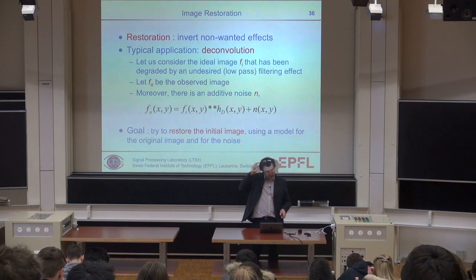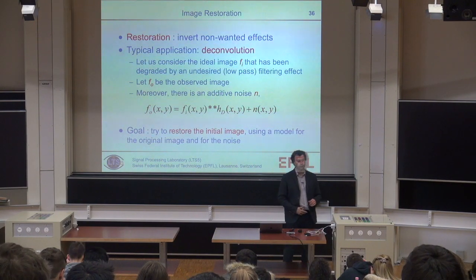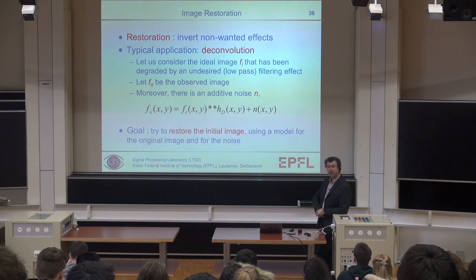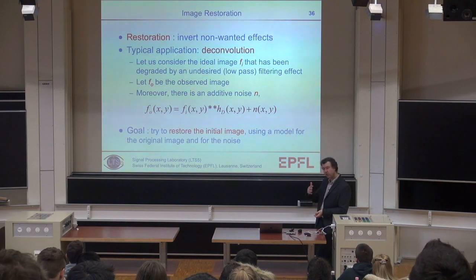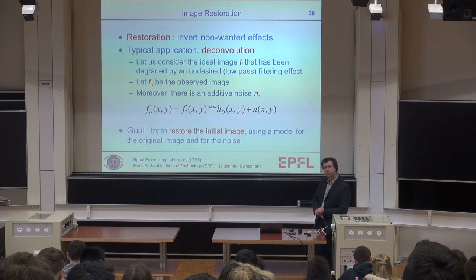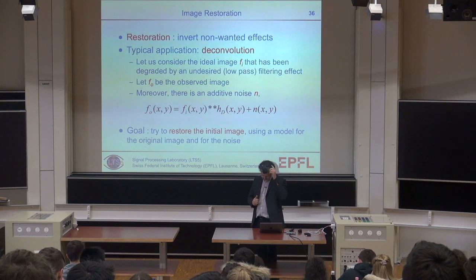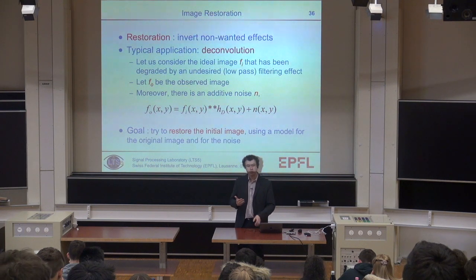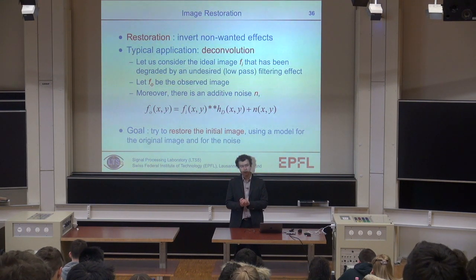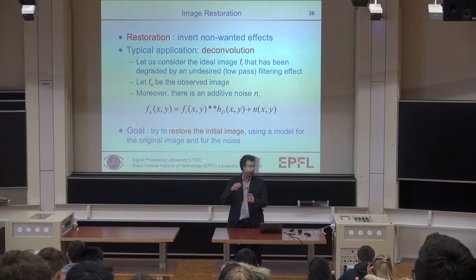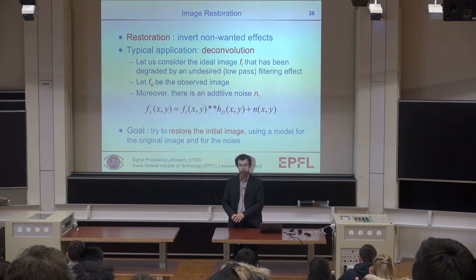But obviously, you want to deal with the fact that you have noise. And now I want to come with you and finish this course with this very interesting domain of image restoration in a more systematic way. Let's try to have an intuition. Let's try to think of what I just said. When do you want to do a high-pass filter? When you don't have too much noise. If you have a lot of noise, you certainly don't want to do a high-pass filter. You want to do more like cutting those high frequencies.